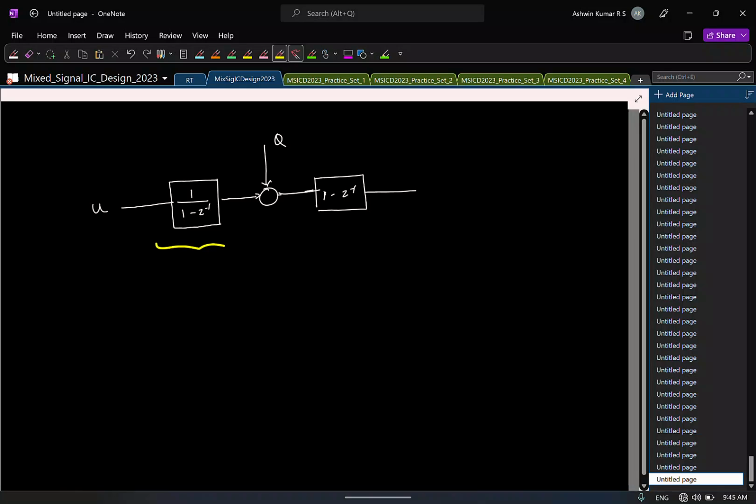For that matter, if you design an op-amp with infinite gain, it is useless in open loop, right? Why do you have infinite gain? To make a virtual ground. You want to have negative feedback systems because you want to enforce a strong virtual ground. That is why you have all this infinite gain. So that is why you can't have this in open loop. In other words, if you implement a voltage integrator like this, it will not work.